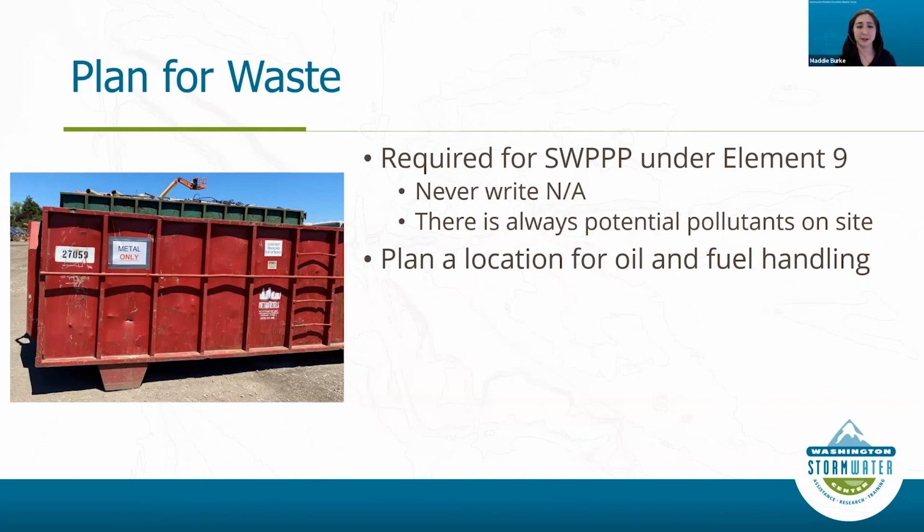Another thing you want to do is plan a location for oil and fuel handling. If you're doing on-site fueling, there's definitely a risk of spills. So you just want to plan a location where you can control a spill, and if there's a spill there, it won't be super serious and accessible to water bodies.